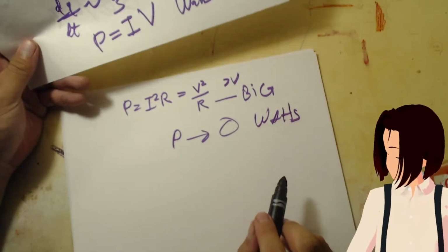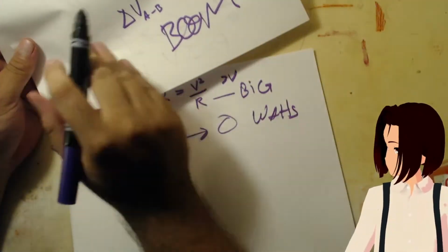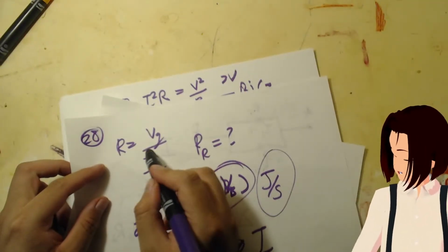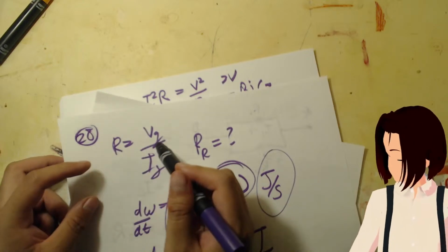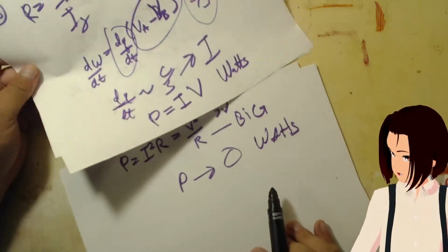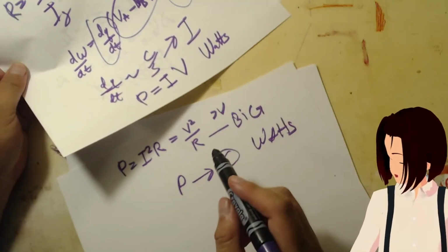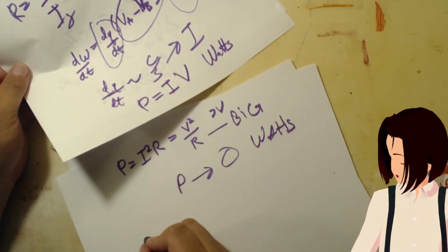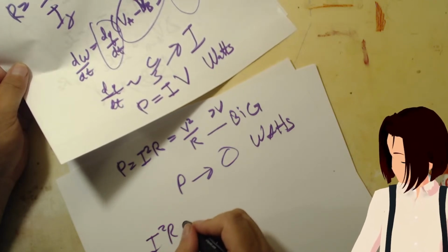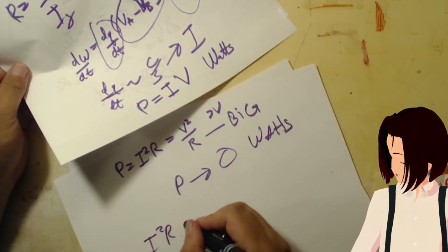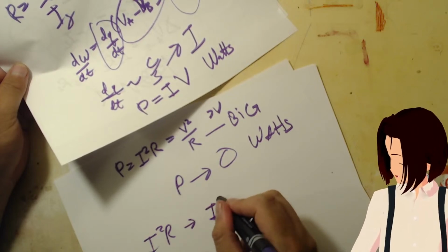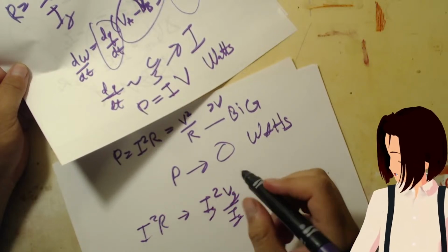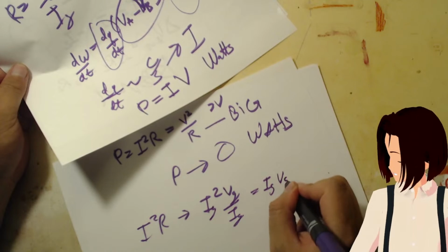So with this, IG, VG, we know that. So we have R. And if we want to calculate the power of R, since we already know it's I squared R, and we know R is equal to VG over IG, we would have I squared VG over IG, and this is really IG, so it's just IG VG.